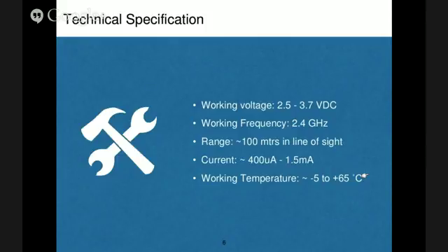I just want to discuss this point also, the range, which I've listed down as 100 meters in line of sight. A lot of beacon hardware have transmission power as a programmable parameter. The range for the beacon's broadcast parameters can be programmed by setting the transmission power value, so that you can set your beacon range for 1 meter or 5 meters or 10 meters, or whatever that hardware is supposed to do with the transmission power.